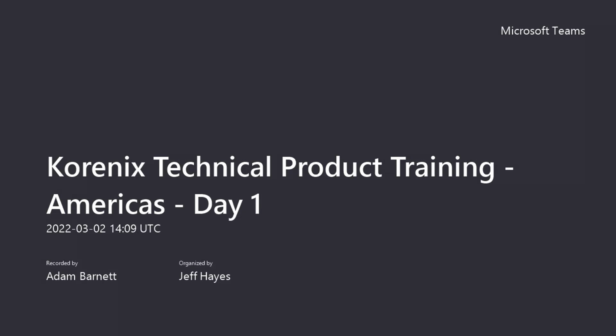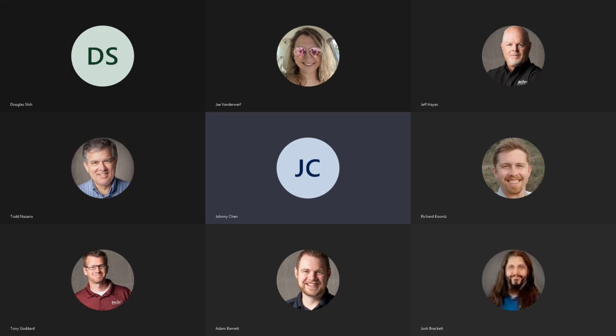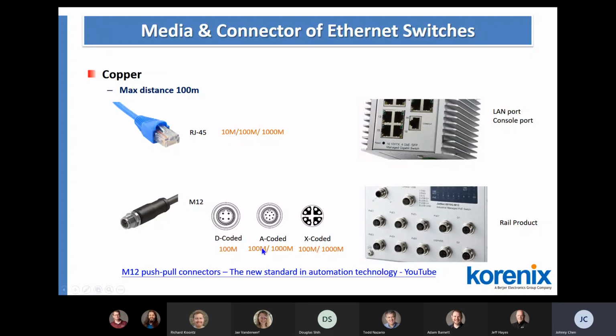Fast Ethernet for the 100 megabits per second. And the A code and the X code support the 100 megabits and also the 1 gigabit for the uplink. So usually we will have the A code or X code for the uplink port, and the other ports with PoE we will have the fast Ethernet port with the D code.